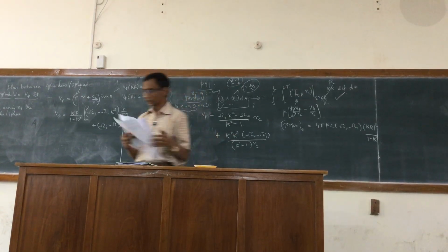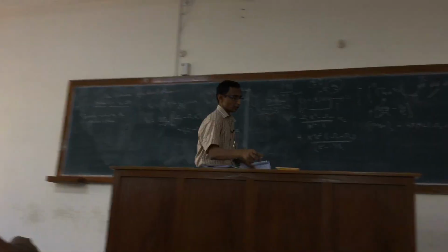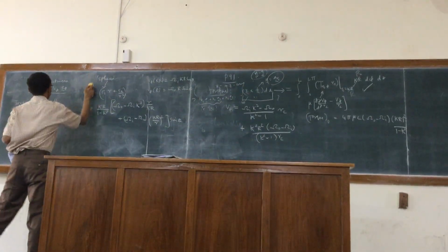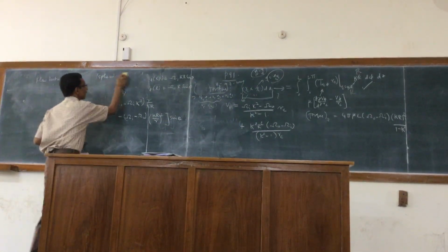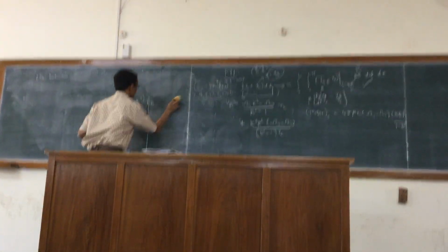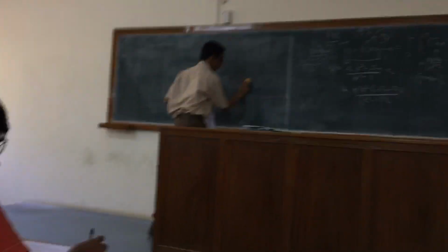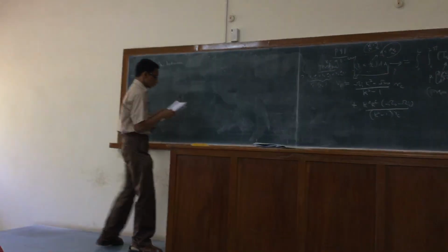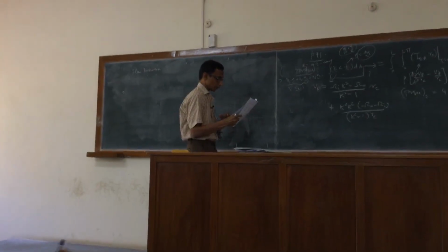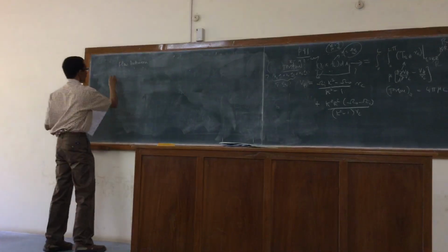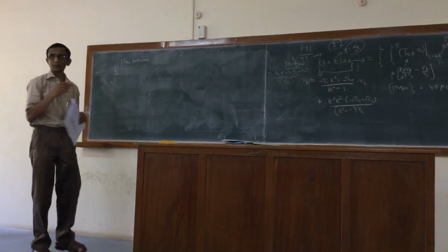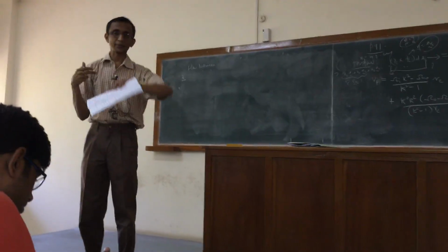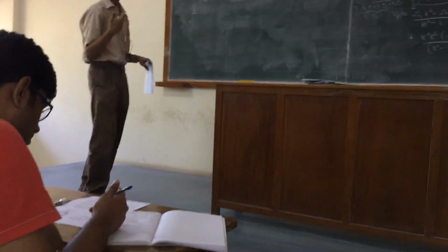There is another interesting problem involving the flow between two spheres, and there we get v theta rather than v phi as the only component. So you talk about a highly viscous fluid flowing between two spheres, and that is problem number 3. Very viscous means the inertial terms can be neglected. That is what is called creeping flow.